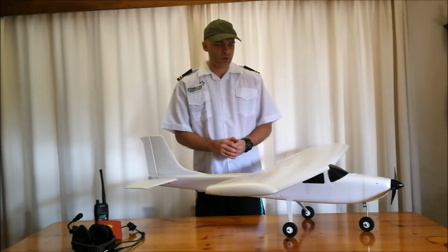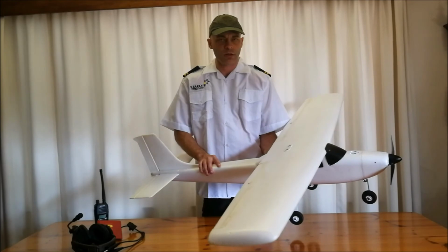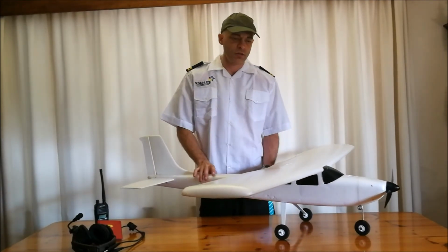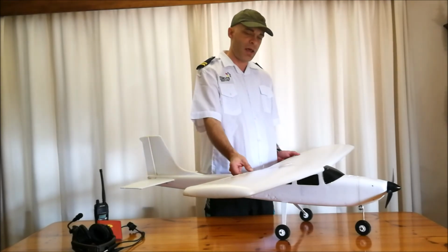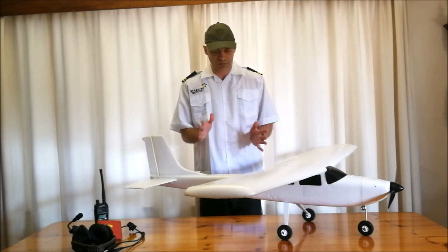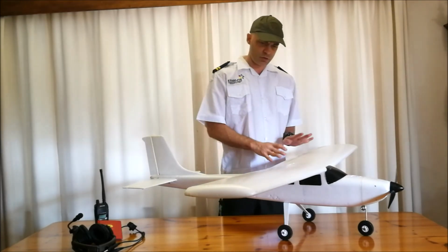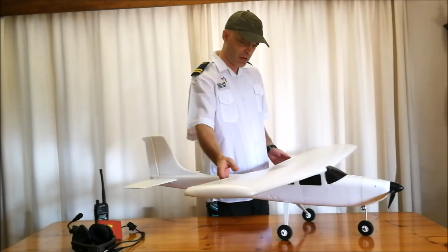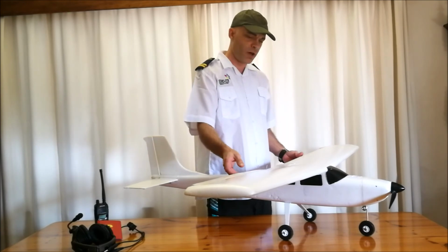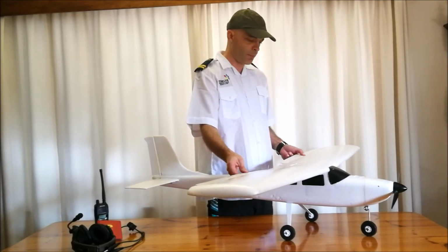And then we've got what's known as roll, which is a rotation about the length of the airplane. The roll motion is performed by the ailerons, which are on the main wing, and they're able to move upwards and downwards. Okay, so now that we've got the three basic motions in place, let's see how it works. With the ailerons, when a roll has to happen, one aileron will move upwards and the other aileron will move downwards.